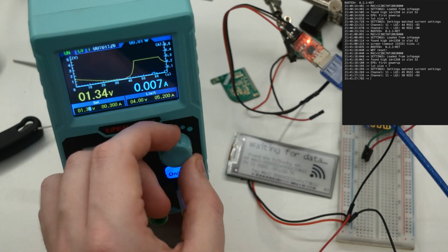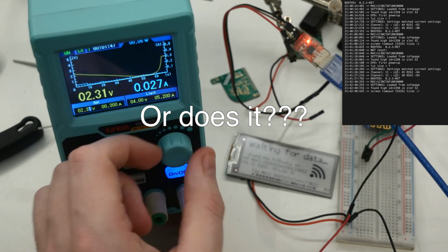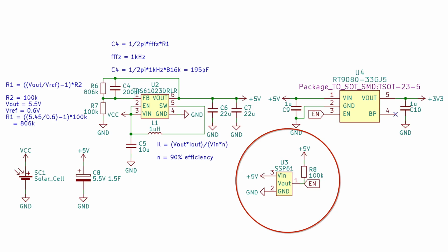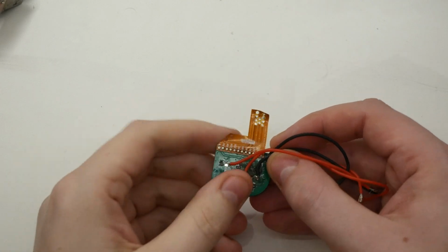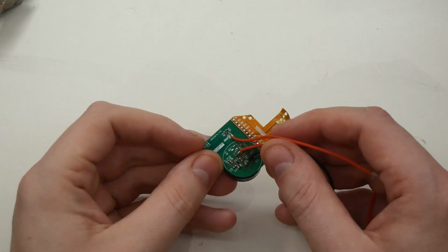Now, in theory, this should be all we need for a first circuit, but since the microcontroller of the epaper display does not have a built-in reset logic, it will lock up if the supply voltage rises slowly. This is the case if the supercapacitor is discharged. Therefore, I use the voltage monitor to turn on the supply voltage only if the capacitor voltage is above 3.3 volts.